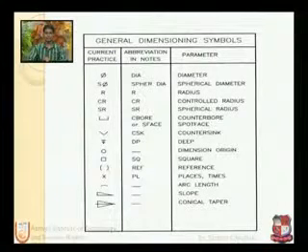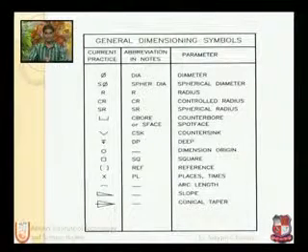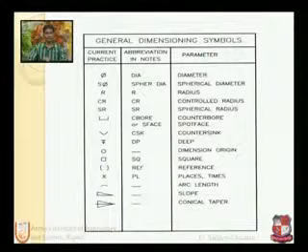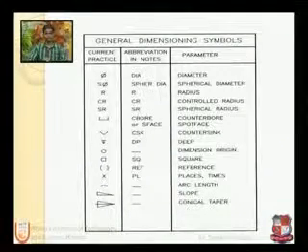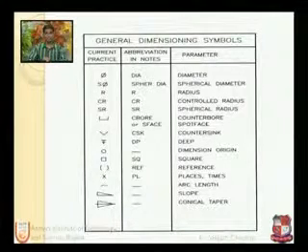And by this means we can understand that there should be a sphere on the drawing. It's written R for the radius, and wherever the radius comes, for example chamfer or fillet or some curvy part, the radius is shown from the center and is written R, and what is the length of the radius. The next is control radius CR, spherical radius SR, and so on. We have this type of special symbols mostly used.